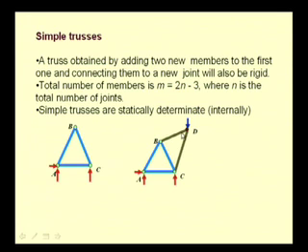If we add 2 more members and a joint, then this structure is also rigid. That is, we replicate this combination of the elements and joints which form a triangular pattern, and if this is replicated in this plane, we get simple plane trusses.